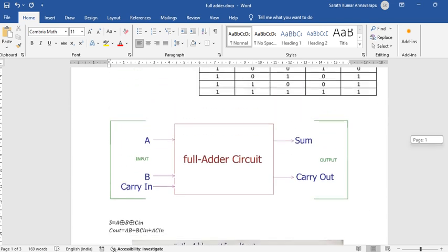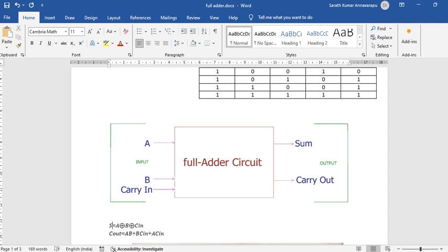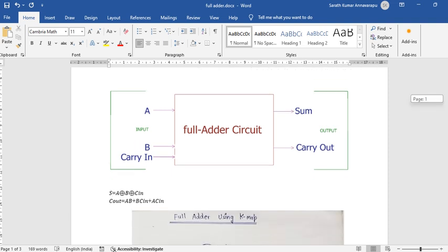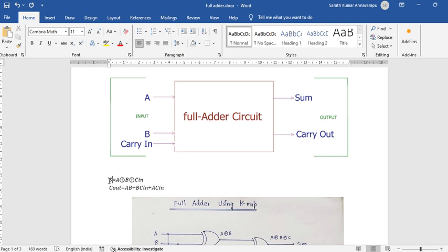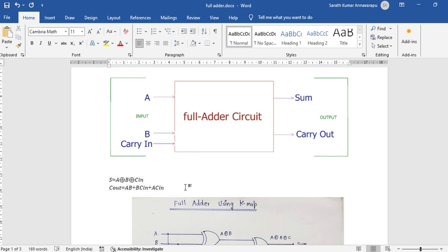In the last video, whatever I covered was the data flow model for the simple AND gate. There I told you that for the data flow, we can simply use these equations in the architecture to realize the structure. The same thing can be followed here. Suppose you want to realize a full adder using data flow, the simple thing you can write in the architecture is sum is assigned with A XOR B XOR C, and C out is assigned with A and B, or B and C, or A and C. So these two lines will give you the data flow model of the full adder.